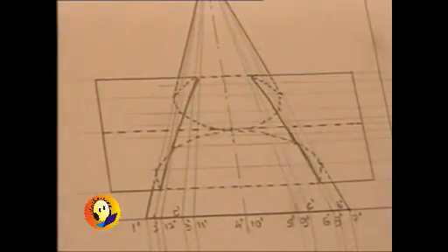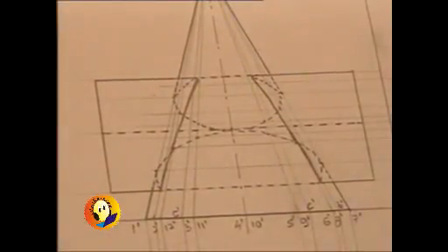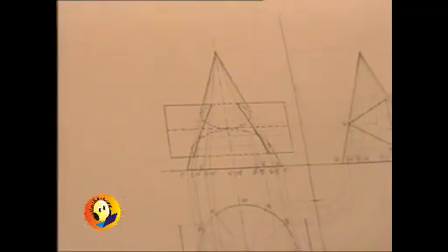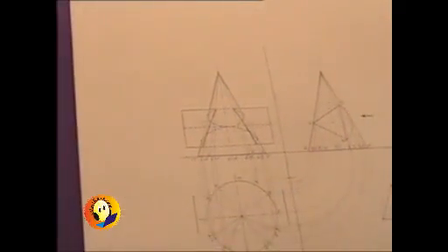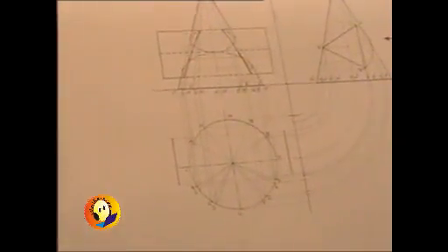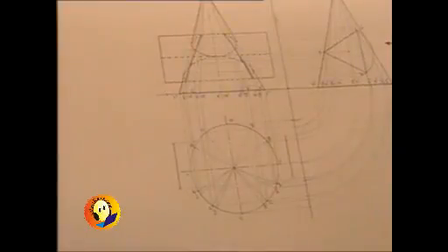Okay. And then all these points should be transferred to the top view, which is one of the very critical parts of it. That job can also be done because we are required to show the curves of penetration in the top view also. In the previous problem it was a cylinder or prism, and we did not have any such curve, but now we will have to transfer these points. So one by one you are required to transfer them, or you can take them from the side view.